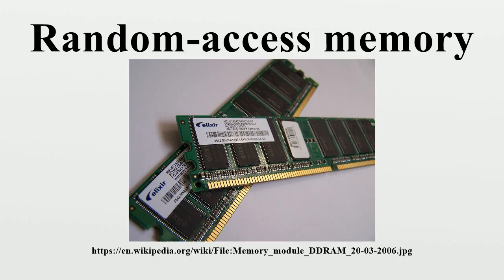Starting in the early 1970s, Robert H. Dennard invented dynamic random access memory in 1968. This allowed replacement of a 4 or 6 transistor latch circuit by a single transistor for each memory bit, greatly increasing memory density at the cost of volatility. Data was stored in the tiny capacitance of each transistor, and had to be periodically refreshed every few milliseconds before the charge could leak away.